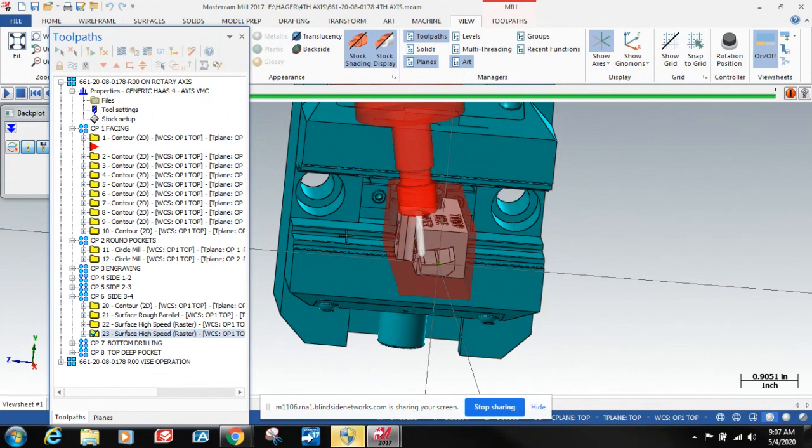You'll see on that project, the helical rotor. They select the surface of that helical rotor and then create a surface milling toolpath, and they actually do that one three times. I think they take it and then transform it to the three different sides. They rotate that 120 degrees and then duplicate it. That is a surface milling project.